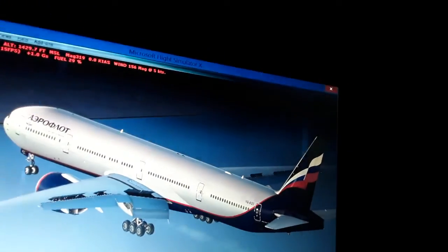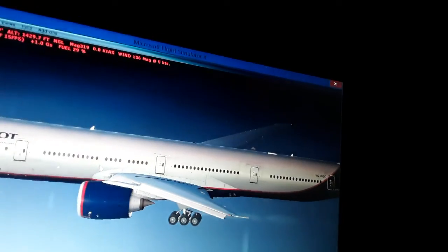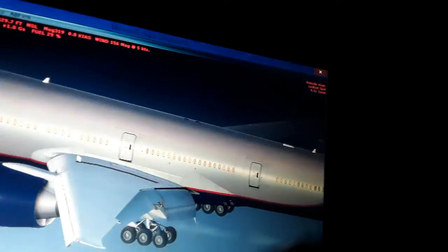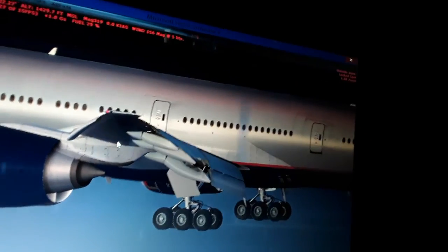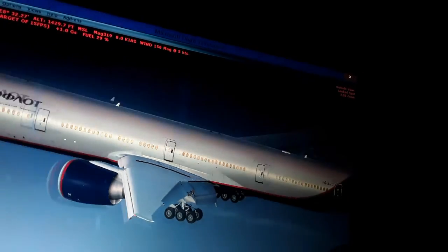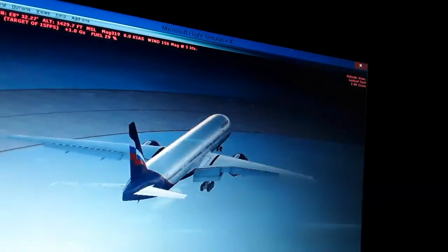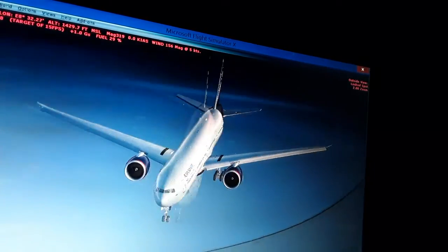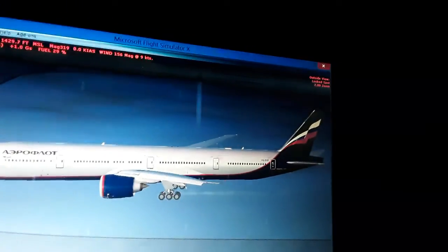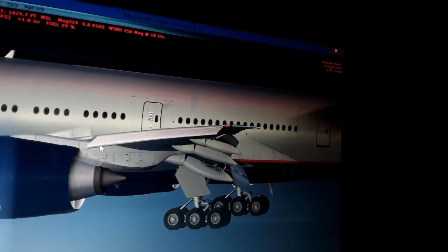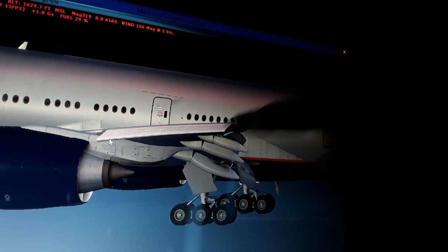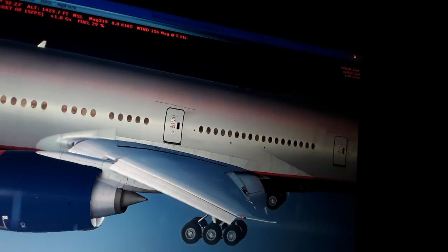So you need to increase the thrust from the engines like this, and you can see here the bottom surface of the wings is actually flatter than the top surface, which is more curved. From the leading edge all the way back to the trailing edge, it creates a stream of airflow when we have 270 kilometers an hour that produces an overpressure. The air travels slower to the bottom of the wing because the surface is flat, and it travels much faster over the top of the wing.